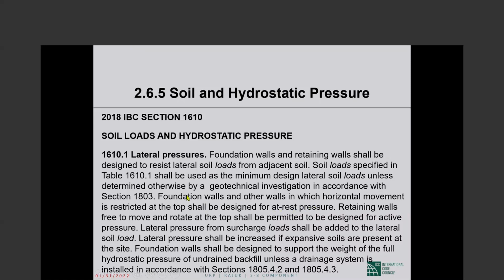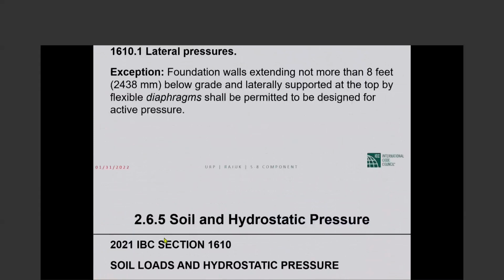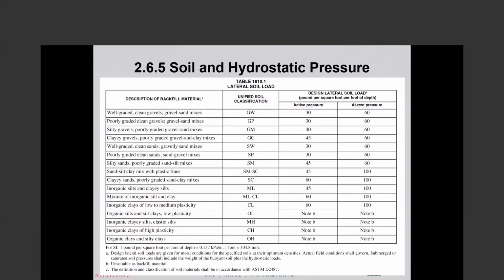Retaining walls free to move and rotate at the top shall be permitted to be designed for active pressure. So there is at-rest pressure and active pressure. So at-rest pressure is here, the active pressure is here.